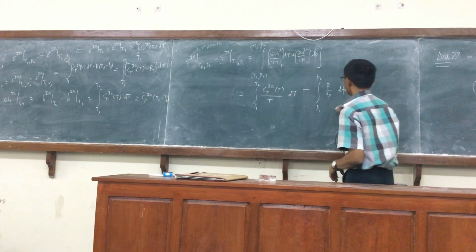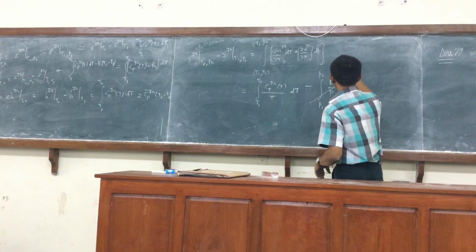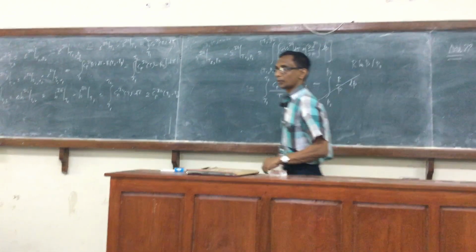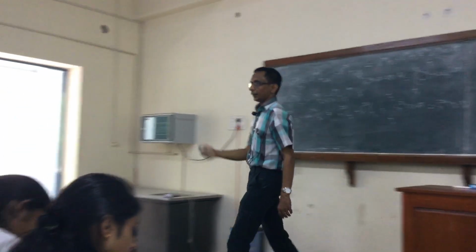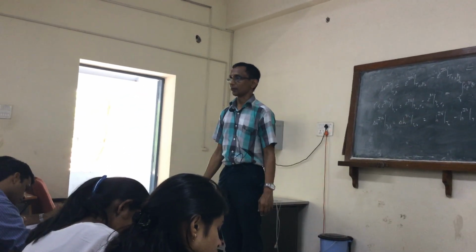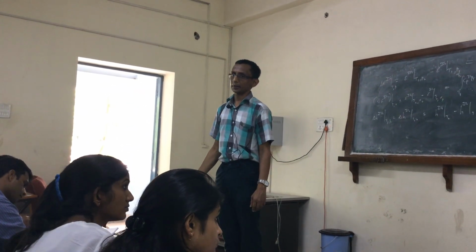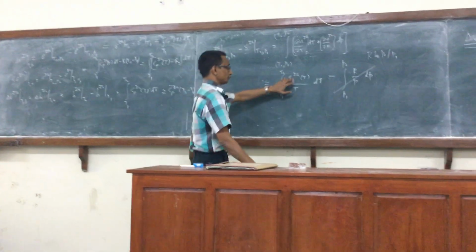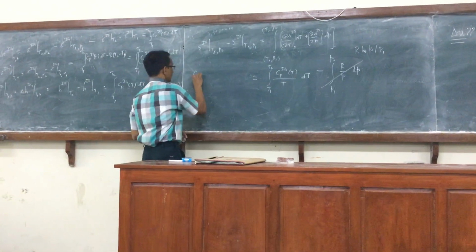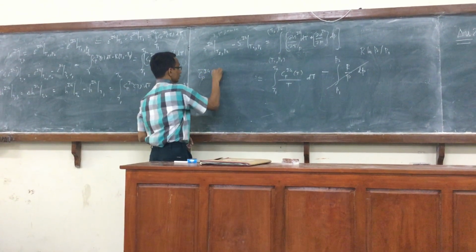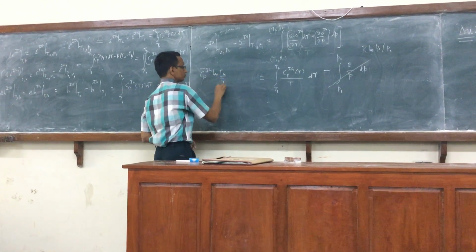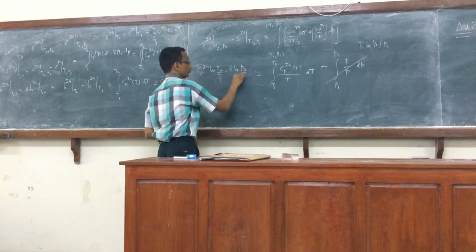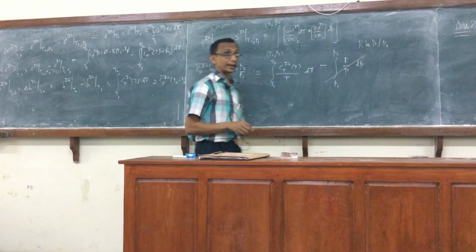This of course can be easily written as minus R logarithm of P2 by P1. And that can be integrated because R is a constant, the universal gas constant. So I can integrate that and give the final form. Of course, if this is a constant also, then I can write it in a closed form.